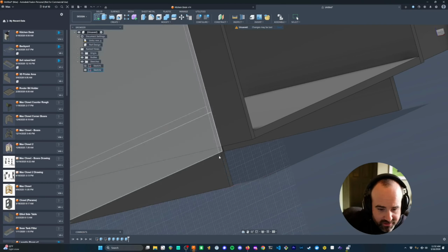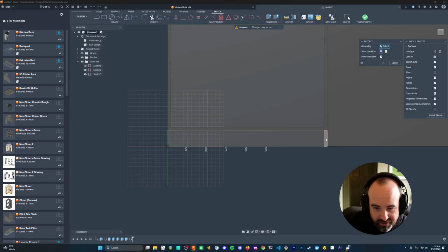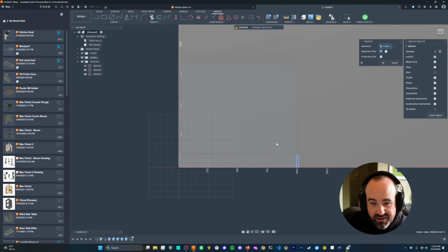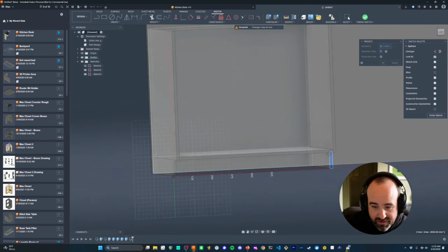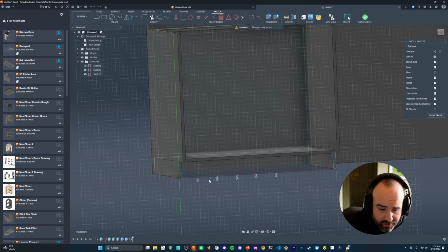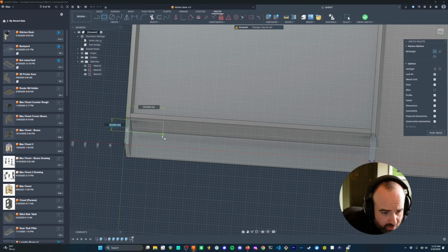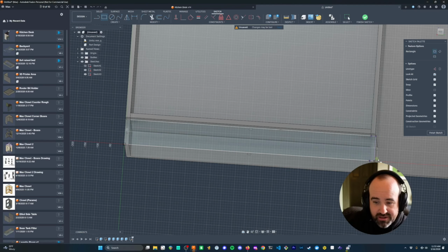We're going to create a new sketch on top of this here, and we're going to project this other piece so that we can use it in our sketch. So P is to project, which lets you project other geometries in the scene and reference them so you can do constraints on them and things like that. So I just wanted to project this other piece here so we can draw a rectangle from that corner to this corner. Notice it snaps for me because it's been projected.